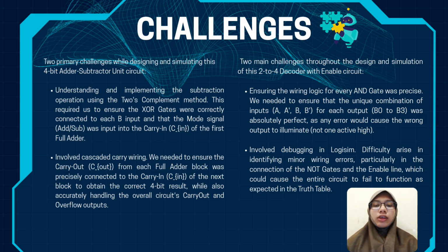These are the challenges that we faced during designing and simulating these two circuits. In the 4-bit adder-subtractor circuit, we needed to understand and implement the subtraction operation using the 2's complement method. This required us to ensure the XOR gates were correctly connected to each B input and that the mode signal was input into the carry in of the first full adder.